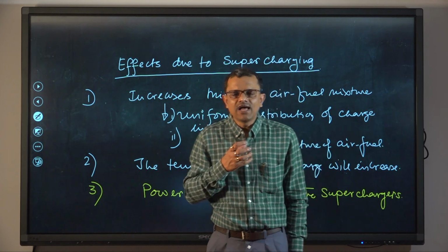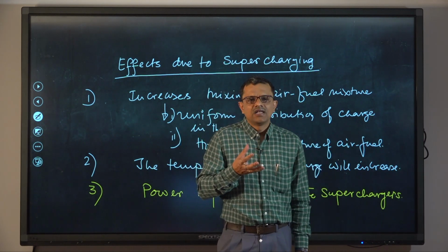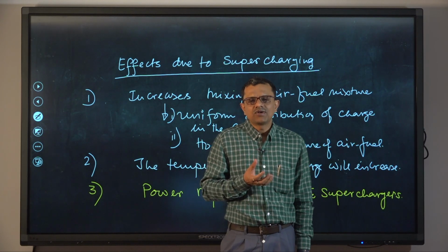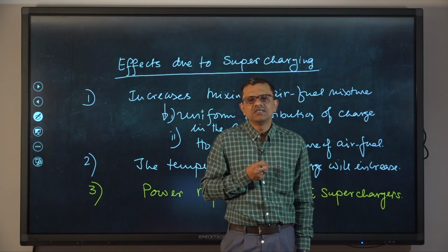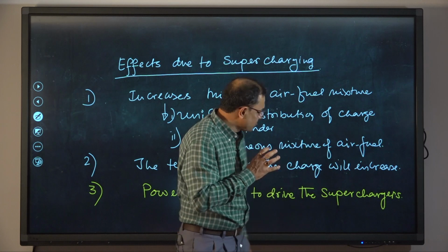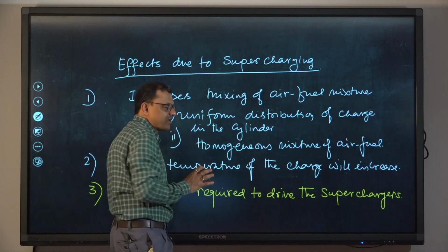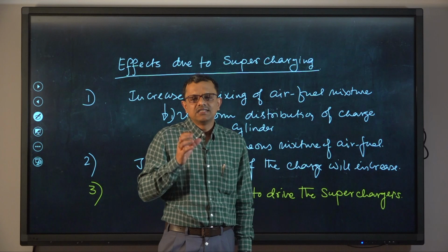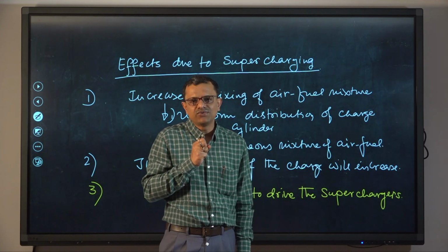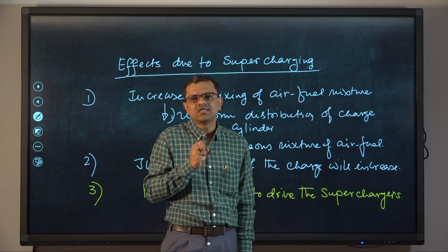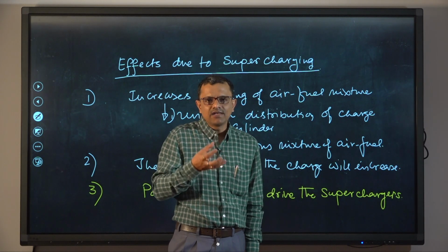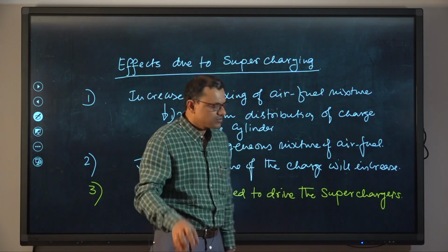So, we will be having a little larger weight of the engine, operation will be noisy, but on the other hand total gain will be 0. So, this part should be taken into account when someone is designing the supercharging unit, so that the power consumption by this unit should not be equal to the power or more power being developed because of this unit.